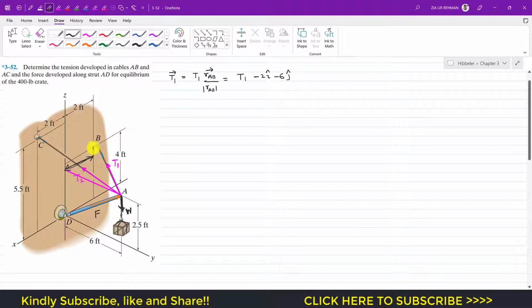And then I need to move this distance. Since point B is at a height of 4 feet, and point A is at a distance of 2.5 feet from the Y axis, this much distance will be 4 minus 2.5. So that is 1.5 feet in the positive Z direction. So I will write plus 1.5K. This whole 4 feet minus this 2.5, so 4 minus 2.5 is 1.5 feet. So this is the position vector from A to B, and then we have to find its magnitude.